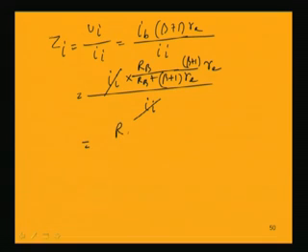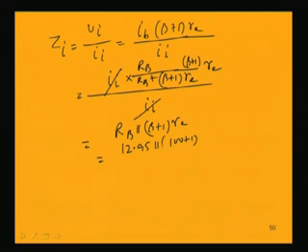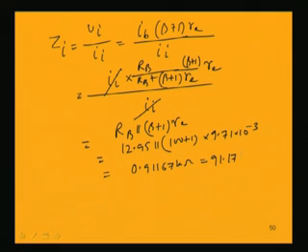So, this is nothing but RB parallel beta plus 1 RE, and if you find out this parallel impedance of 12.95 and 100 plus 1 into 9.71 into 10 to the power minus 3, that comes to 0.91167 kilo ohm. So, finally, we get that it is 911.17 ohm.